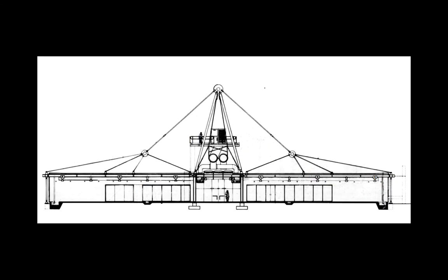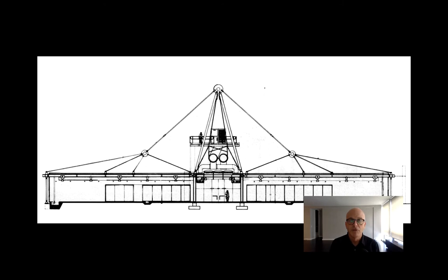You can see some of this at work if you look at cable structures in particular. Here, this is one of my favorite buildings because it's just a structures lesson kind of brought to life. This is the Patscenter in Princeton, New Jersey, which was done by Richard Rogers in the early 1980s. And Rogers basically designed a structure that was a whole set of free body diagrams and vectors. These lines are all what we call tension elements. They're like cables. They're actually steel rods, but they work like cables. They're resisting by going into tension, right? So we can think of them as being pulled from both ends.